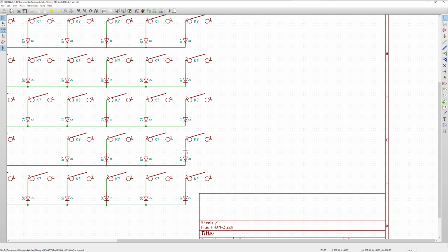Okay, so if this was a single 2U key between these two key switches here, it would run off one of these rows and columns regardless, because it was a single switch. It's just physically placed elsewhere. When we turn this into the 2 switch situation, one of these will be in the middle of the 1U position, the other one will be in the middle of the 1U situation. So we need a physical extra map for it to be in the middle of a 2U position, but it would still be linked to just one switch. When it comes to programming, if you don't use that second switch, you just simply don't assign anything to it.